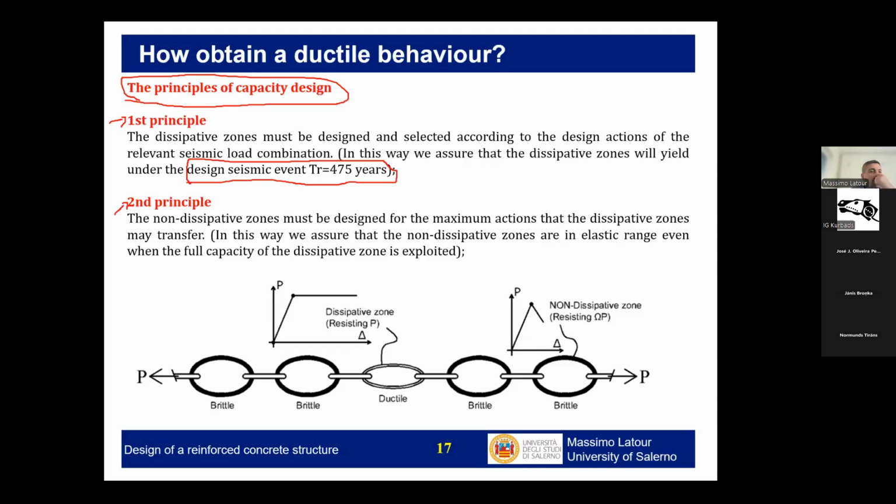So ideally, we will design the structure to have some hierarchy. How do we define the hierarchy? So we have to be clever here, because we have to think as a matter of principle, first of all, as a seismic engineer, what is the part of the structure for which it is most favorable to have a concentration of the plastic demand.